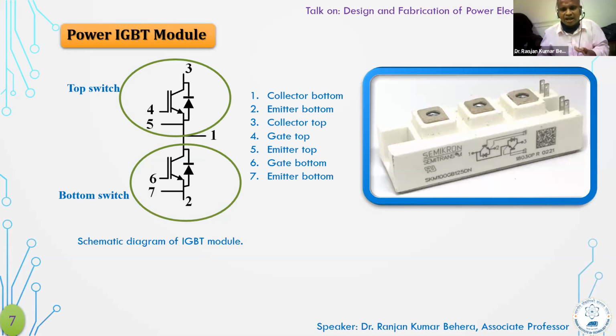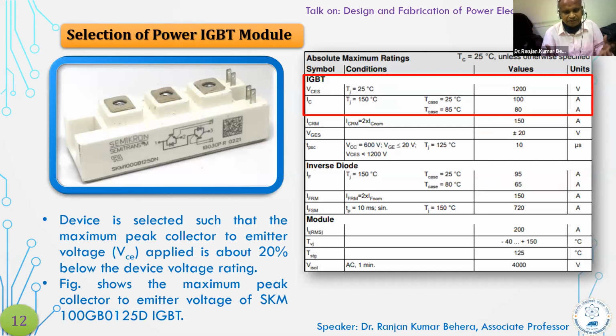That is how I take this IGBT module. I will take them and cut this IGBT module and show how the microelectronic circuits are designed and where they are. And there are a lot of liquids; why these liquids are provided. So they learn many things in the class itself. They take one or two days to study, and then I give the data sheet. I tell what these parameters are, why they are given, what the safe operating area is. They try to understand this.